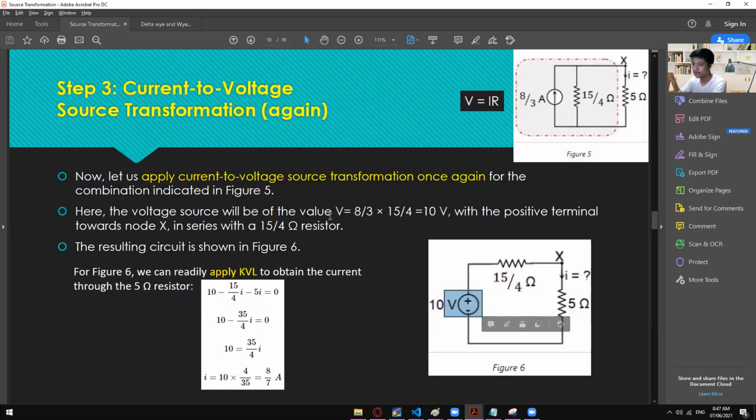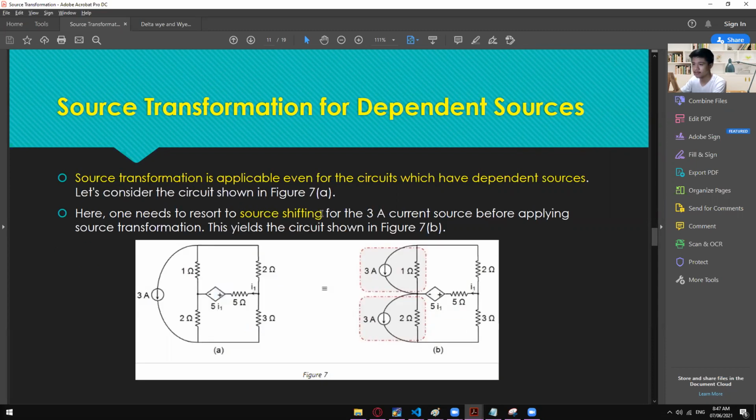If it's a diamond like this one, most likely it is a dependent source. This one has an additional variable, which is I. So this voltage right here is dependent on this current right here. This 5 volts will still vary depending on the current that will flow onto this node right here, or the I1.